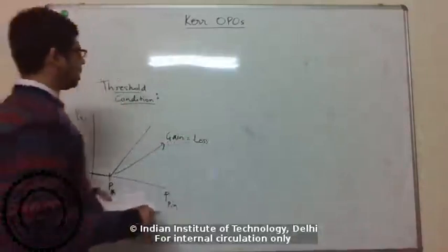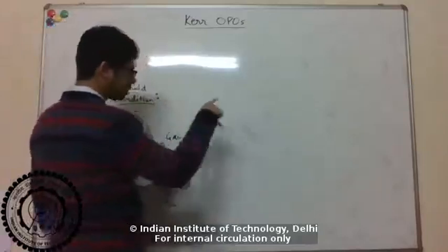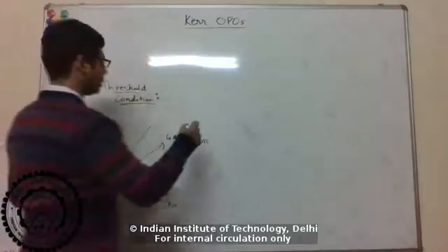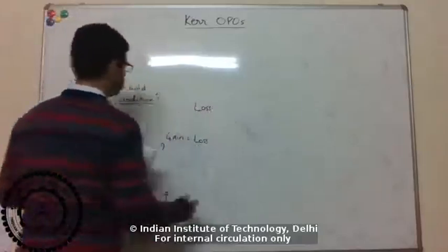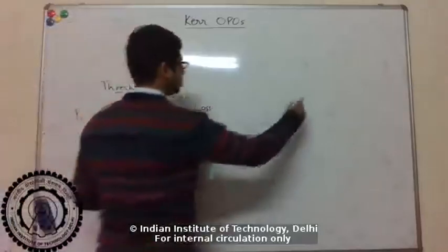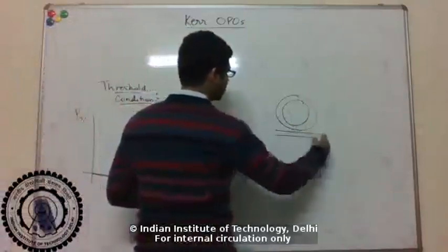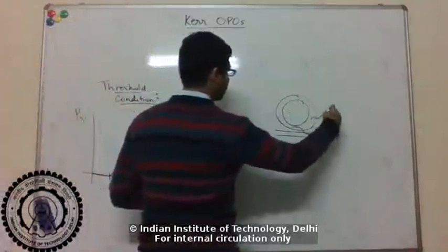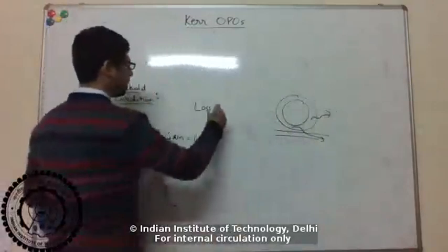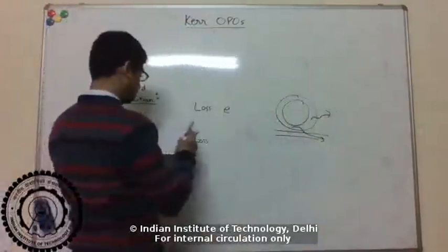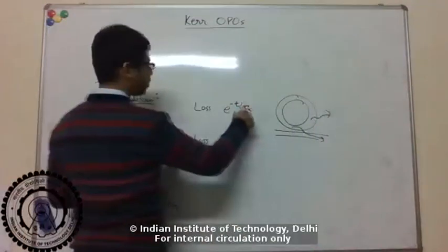Recall how power is lost from the cavity. The loss is happening because photons are leaking out from the cavity, either due to scattering or leaking out into the waveguide. The energy decaying from the cavity we can write in terms of the cavity lifetime, which can be written in terms of the Q factor.